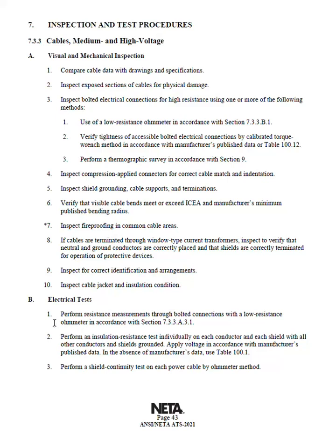I'm not going to go through all the stuff on cables, but it says perform an insulation resistance test individually on each conductor. And what we're trying to do is test the insulation resistance of the insulation itself. Okay. And so in the absence of manufacturer data, use this table.